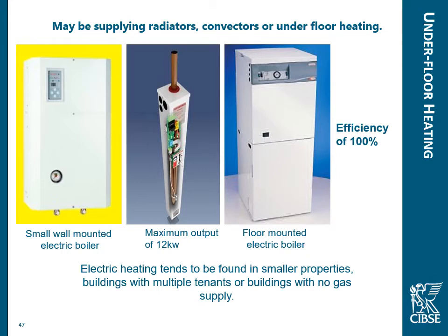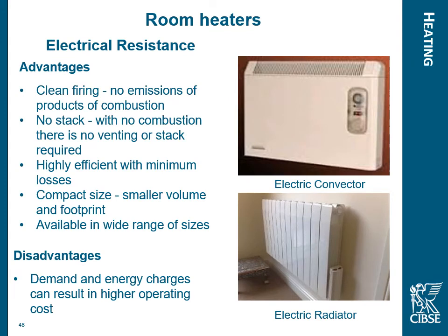Now, electric heating on well-insulated buildings is not too much of an issue, mainly because if our building is well insulated, we're not using much electric, so although it's slightly expensive, we're not paying that much extra there. So the good thing about electric heaters: relatively simple, clean firing, no emissions, no problems about running gas supplies, no problems with flues coming out into areas. The disadvantage though, higher energy charges can result in higher operating costs there.